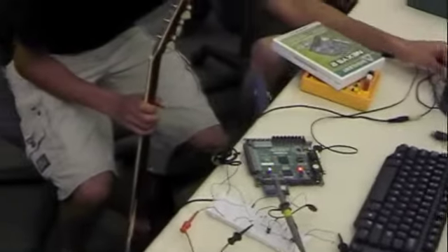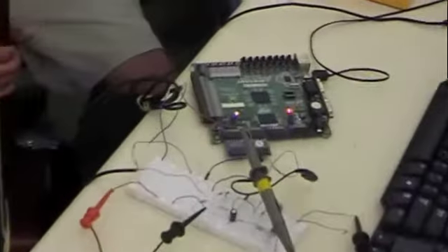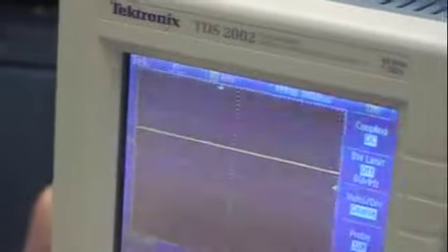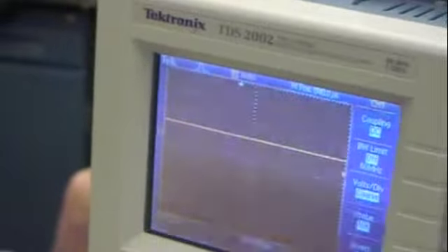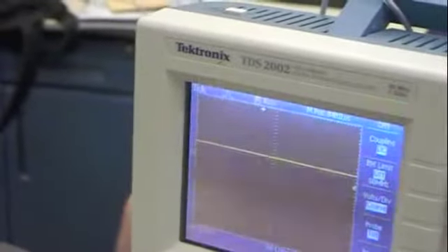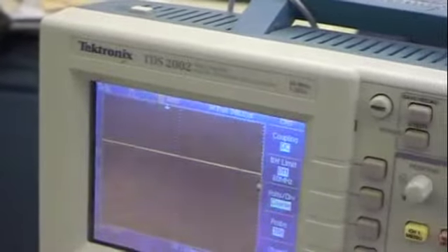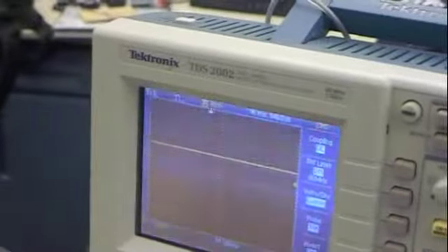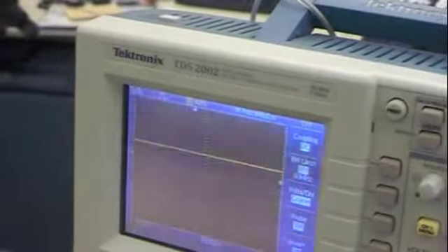Alright, go ahead. Turn that on. Okay, so if you look at the oscilloscope over there, you can see the waveform coming out of the guitar. Right now it's set to clean, and if you play too loud, it will distort, even though it's on clean, because the output from this is really variable. I measured it to be maximum 60 millivolts peak to peak, but you can go beyond that if you strum really hard. So it might distort just because that's the maximum range of the ADC.